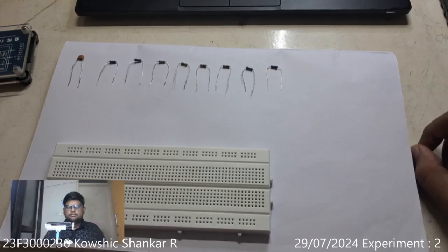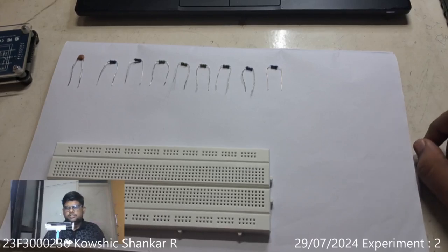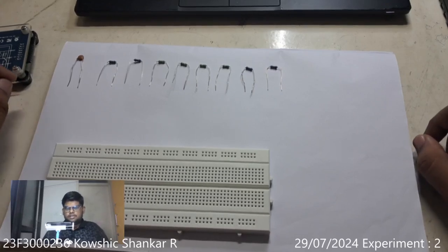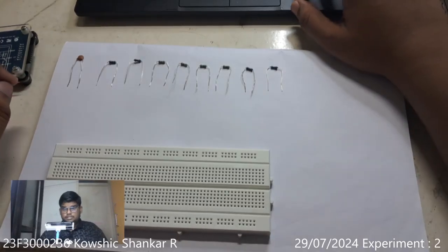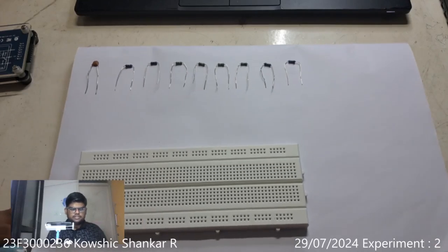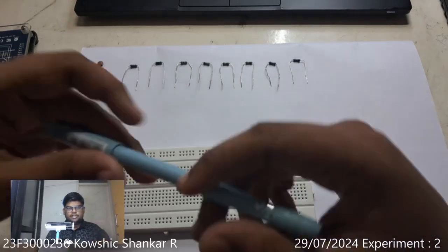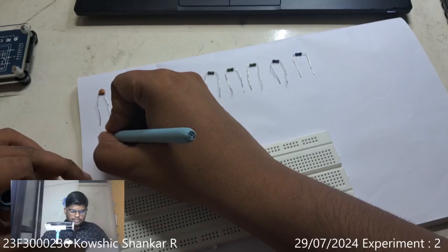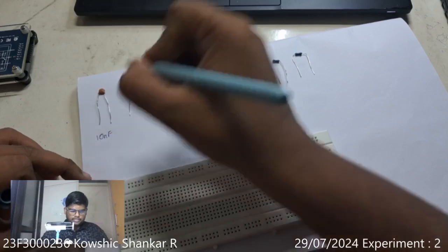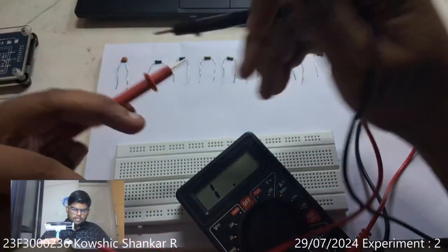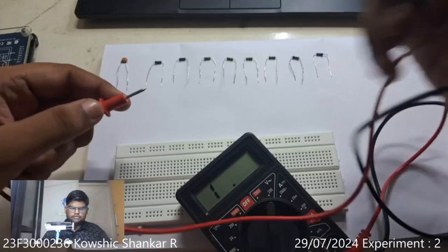We require a 400 kilo ohm resistor, two 1 kilo ohm resistors, two 10 kilo ohm resistors, a capacitor, a multimeter and an analog board, which is the ADALM kit given. The capacitor which we are going to use is 103, which is 10 nanofarad in capacity. As I do not have a multimeter to measure the capacitance, I am just going to take it as 10 nanofarad. Now I am going to measure the resistance of each resistor and note it down in this note.